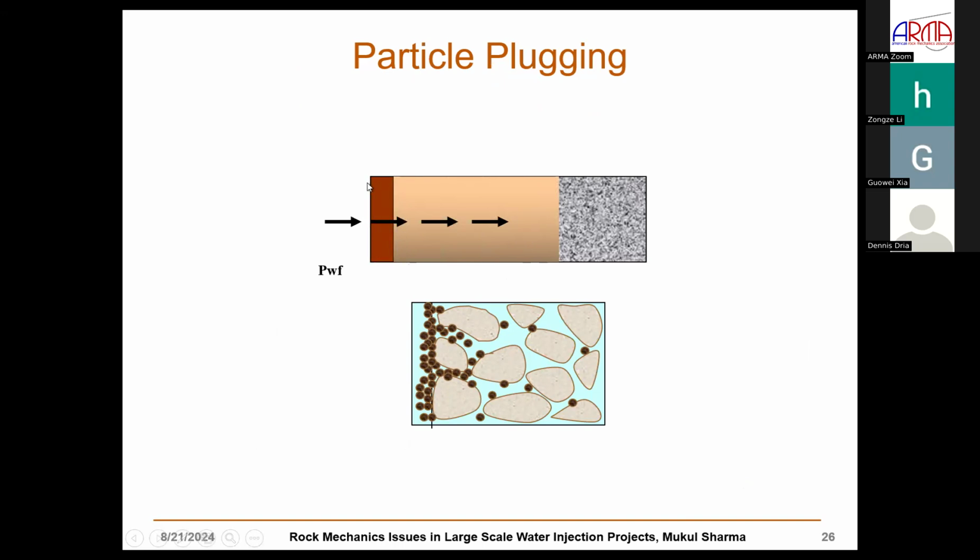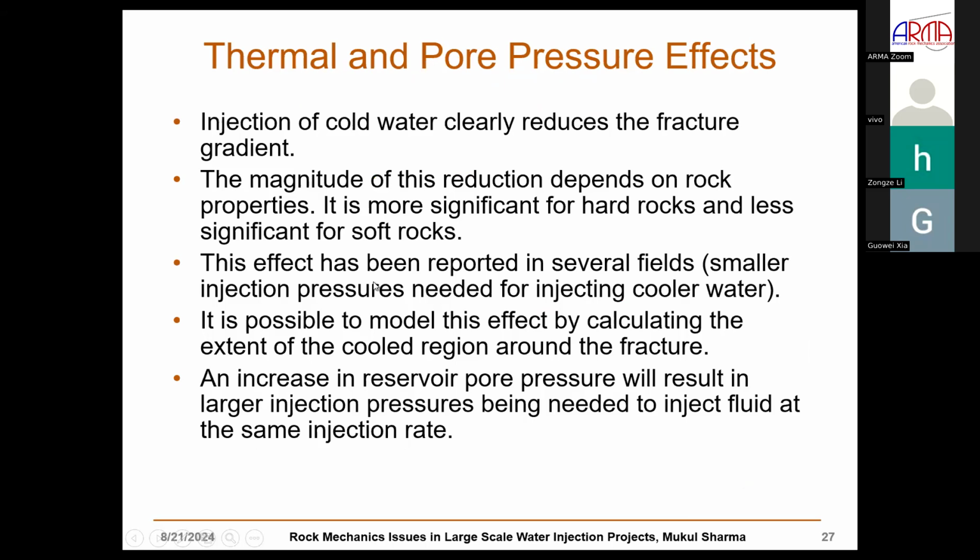because this external filter cake that forms offers a flow resistance which increases the pressure in the fracture, reduces the leak off, and essentially it's a fluid leak off control material in hydraulic fracturing terms, right? And this is an extremely important effect in large scale water injection projects.